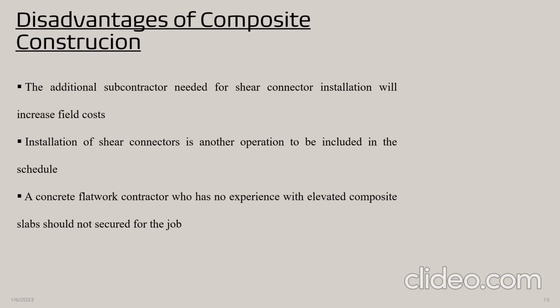Disadvantages of composite construction over RCC or PCC. The additional subcontractor needed for shear connector installation will increase field cost and duration of the project. Installation of shear connectors is another operation to be included in the schedule, which increases the overall duration of the project. A concrete flatwork contractor who has no experience with elevated composite slabs should not be secured for the job.